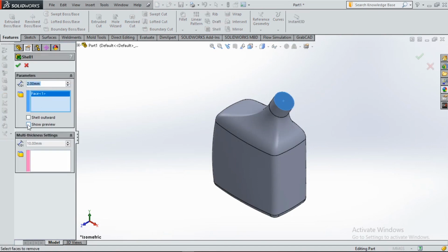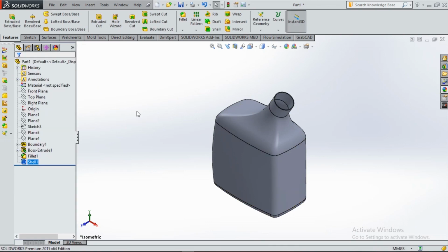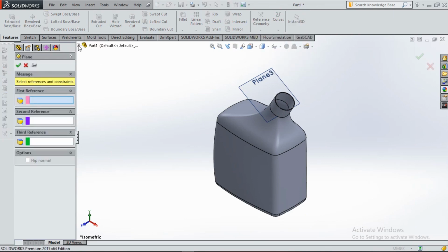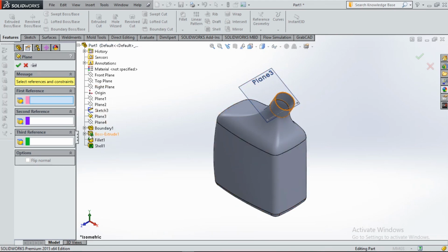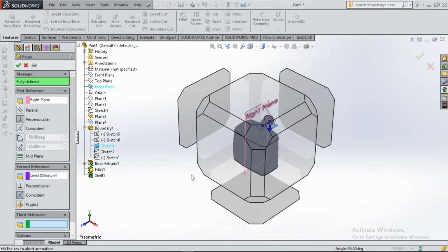So I hope this video explains a lot of how to use the boundary box based command. It's quite easy to use actually, so just make sure you follow the right steps. Create your closed loop sketch on different planes first, then you make your open loop sketches. Afterwards, you make your open loop sketches have a piercing relationship with your closed loop sketch you have created, and then you add the boundary box based command, whichever way you want to do it, either by selecting the closed loop sketches first in one box then going on to select the open loop sketches in another box.